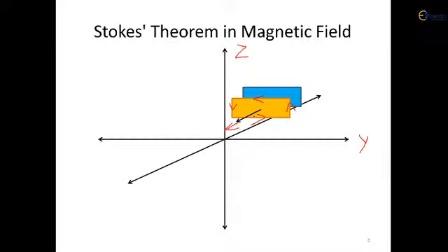Now first of all we consider the surface integral. The surface I have already shown to you with the yellow color here. Here we need to first find the current density before finding the total amount of current, because we have been provided the vector representation for the magnetic field intensity, and if we find the curl of this given vector, that will be nothing but the cross sectional current density expressed in terms of ampere per meter square here.